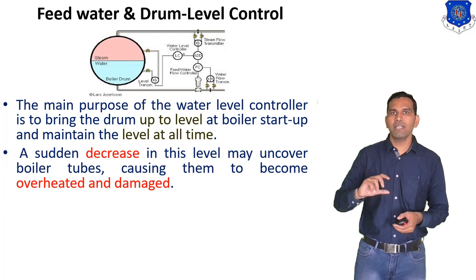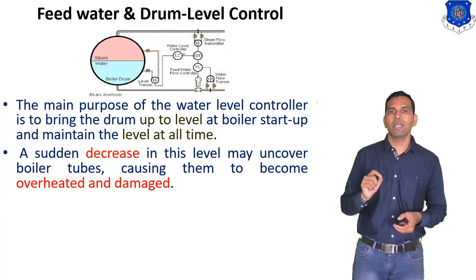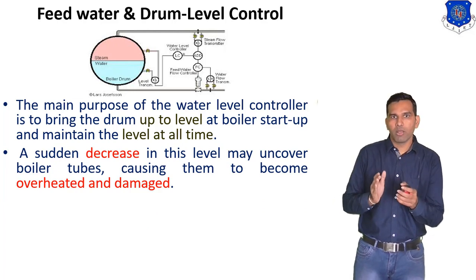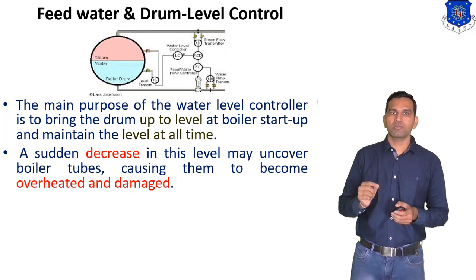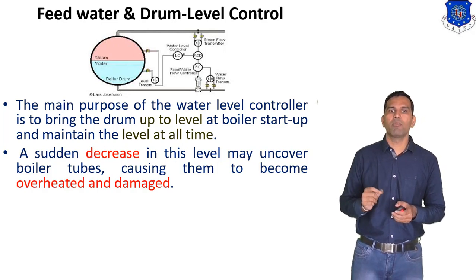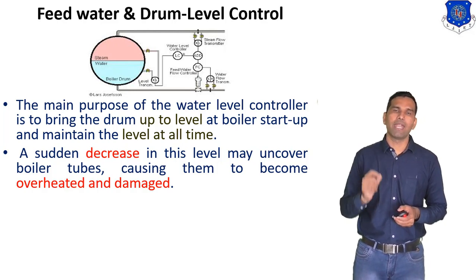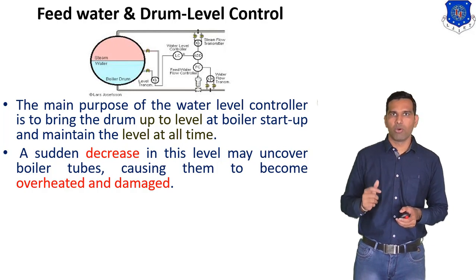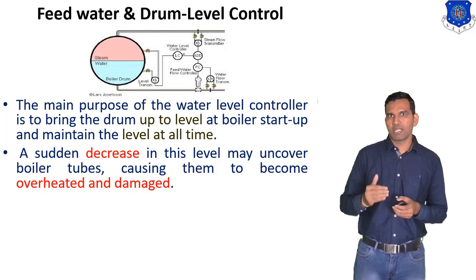Then, a sudden decrease in this level may uncover the boiler tubes, causing them to overheat and get damaged.